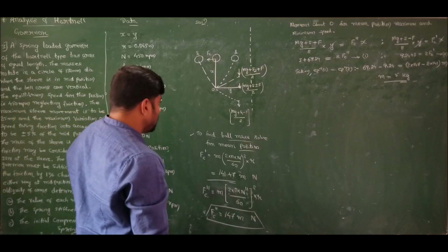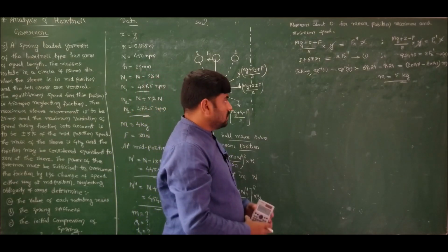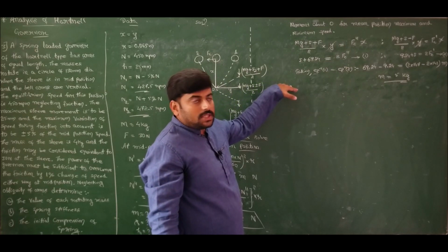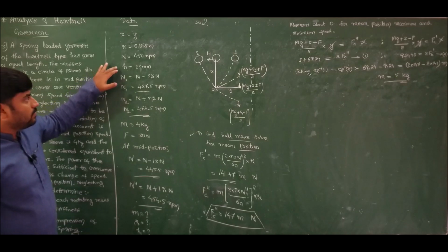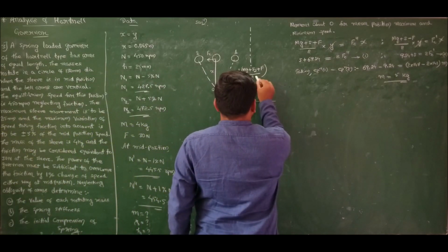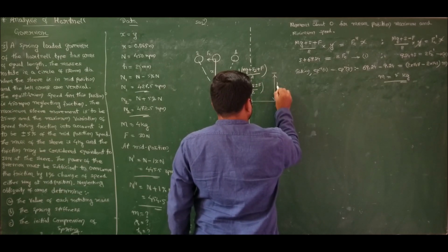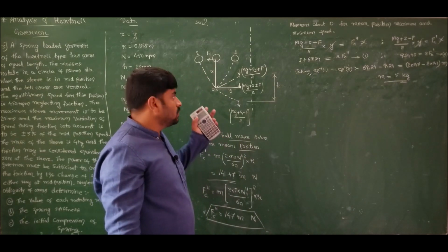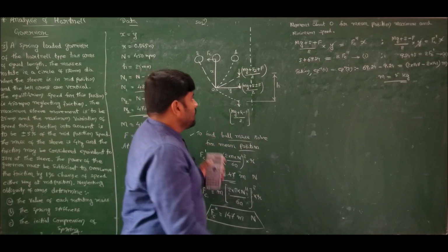Now to find the spring stiffness, I want the general expression, that is S2 minus S1 by H. H is already known. Total lift is given as 25 mm. So H is already specified for us. Therefore I should find S1, S2 and H, where S is the force exerted.